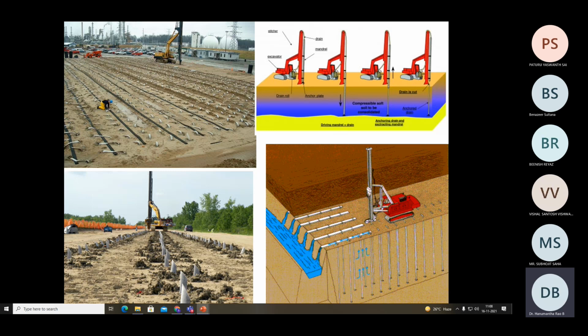If you recall, right on top of the natural ground, we always have to provide some kind of blanket layer. Therefore, this protruded PVD will be directly inserted in that blanket layer. In the above picture you can see this is some kind of sand, and you can also see the upward movement of water squeezing out from the ground or some kind of dampness.